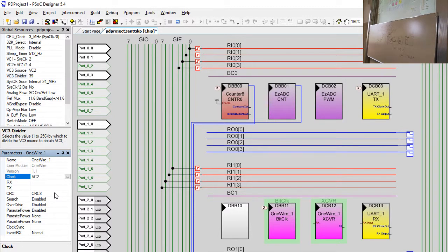Okay, and then fortunately, SPI and I2C bus are synchronous buses. They have clock rates. There you have more flexibility. But this asynchronous data communications, you really have to be careful of fixing the clock rates exactly. Yes, you have a question.